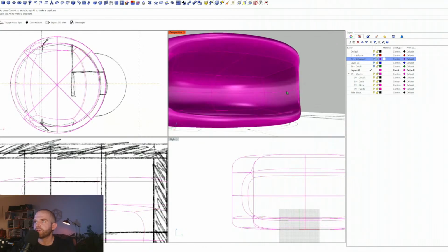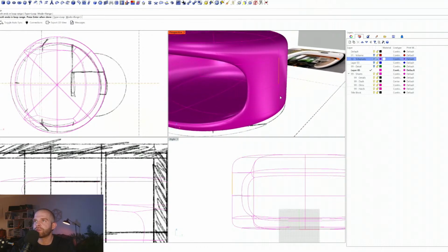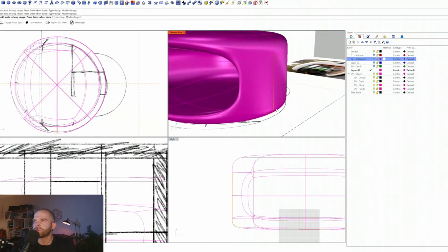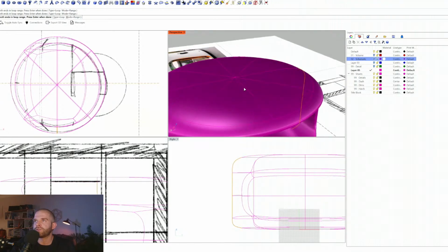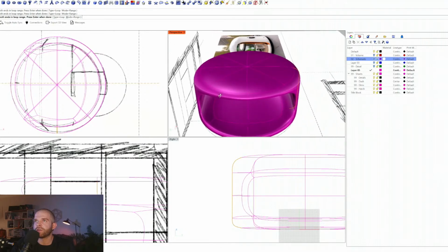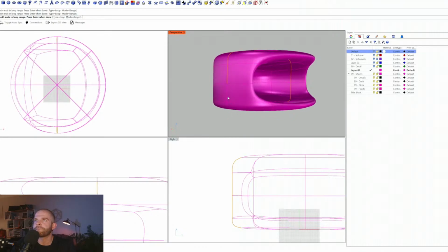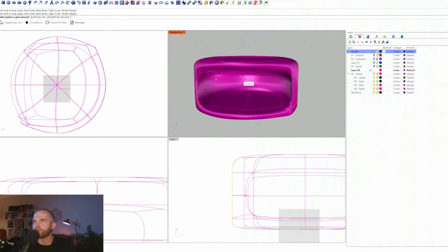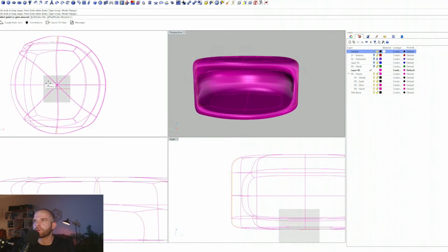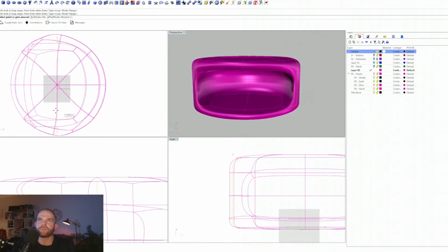So if I wanted to mess with these edges a little bit more, we'll do InsertEdge once more. And now if I want to do it to both sides and I want it to be mirrored, I should be selecting it on both sides. So we'll select that edge and this middle edge. Let me hide my reference. Cool. So if I go to plan view, you'll see that they're actually opposites, right? They're moving in opposite directions.